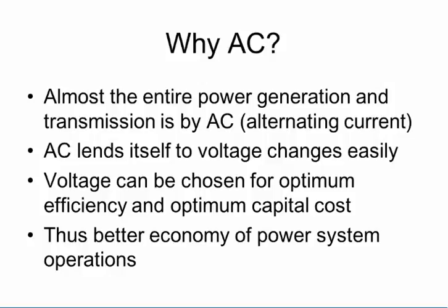So the idea is that we use the AC waveform, and the main reason for that is that when it is required to deliver energy over long distances, it is able to be transformed into higher voltages and reduced current, thereby reducing the losses in the system.